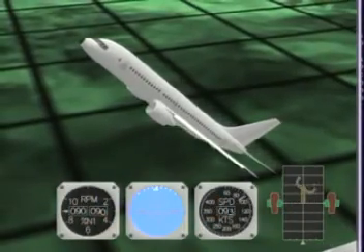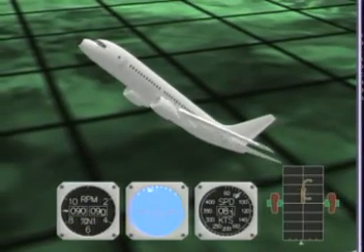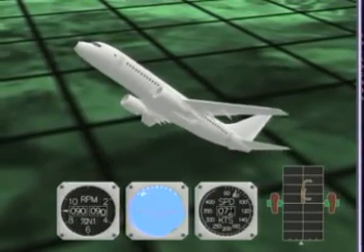As you've seen, there are specific recovery techniques that you can use if your airplane becomes upset, no matter the type of upset. Nose high, wings level; nose low, wings level; high angle of bank. You must take control of the situation and you must react quickly and correctly. Let's review the nose high and nose low recoveries one more time, incorporating bank angles.